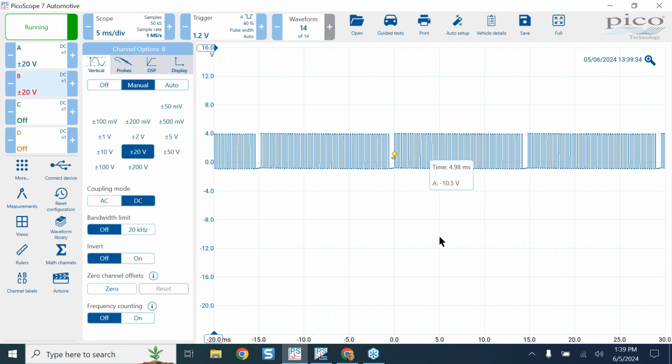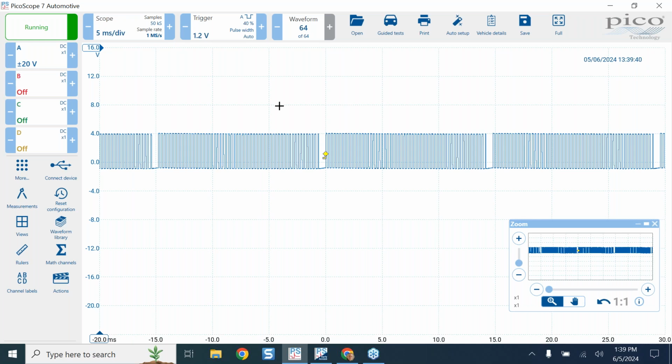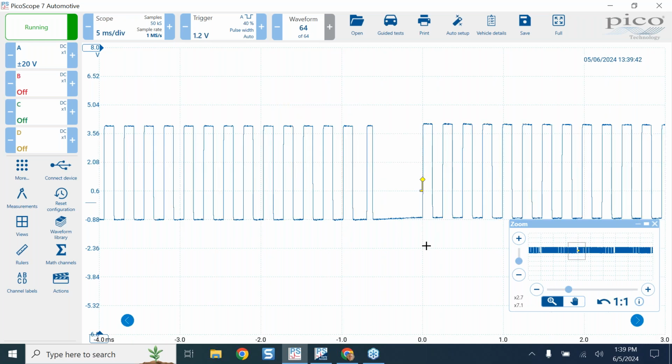I had just channel A. I just had my crank, and I had gone ahead and set my trigger up. I did that, of course, by measuring a good tooth versus the wide one that my eyes wanted to trigger on. That's where I wanted to stabilize this point at.